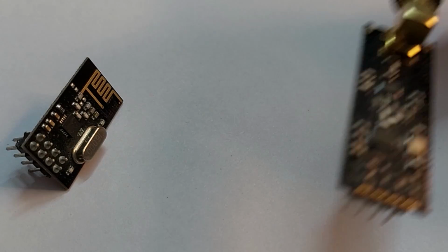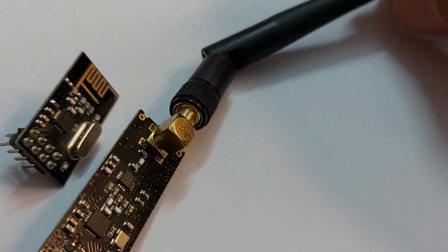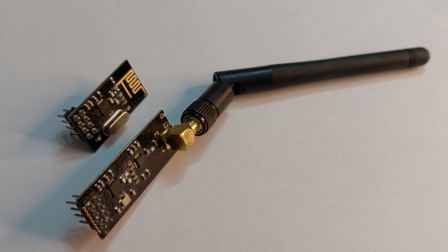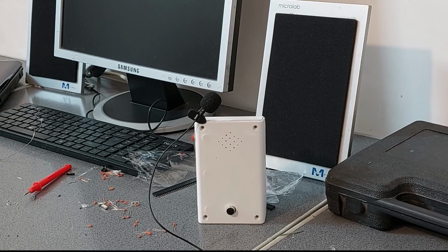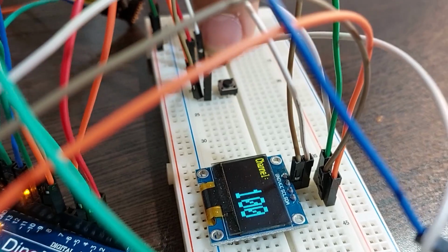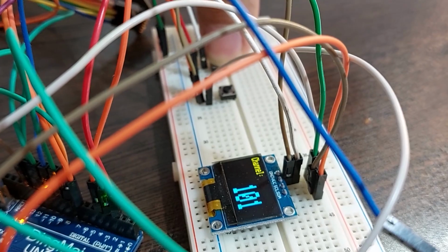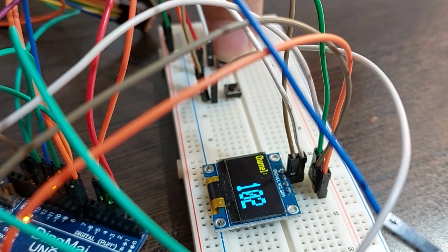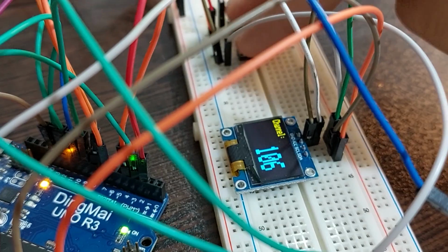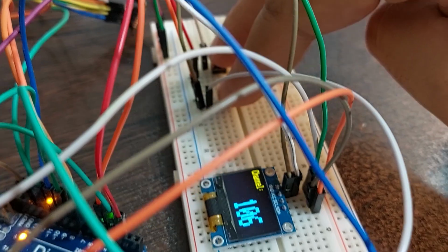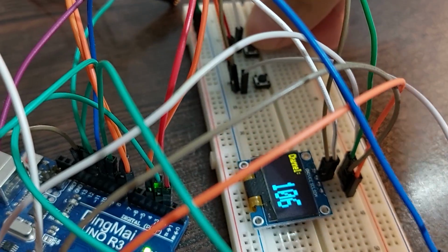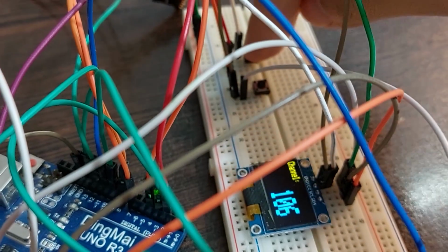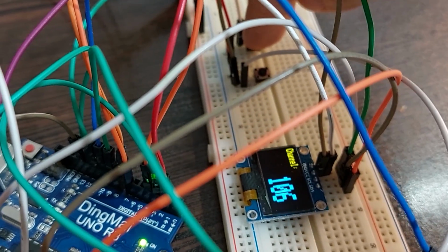The NRF24L01 module selects an empty channel to send and receive data so that the transmitter and receiver are synchronized. So far the project is working well and there are no problems. But as always, I would like to have a display and select the channel I want with a microswitch. I did this before, but I had to select the channel before connecting, and after connecting I was no longer able to change the channel. This means that we had to turn the device off and on to change the channel, which was not good